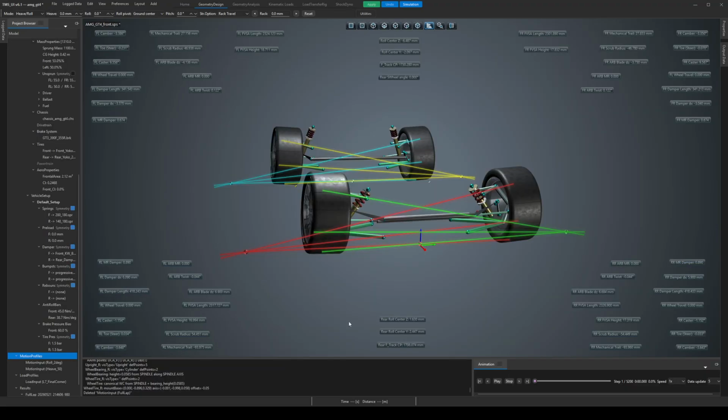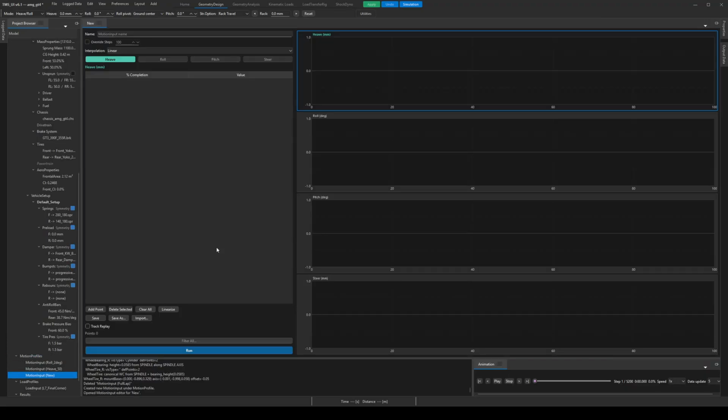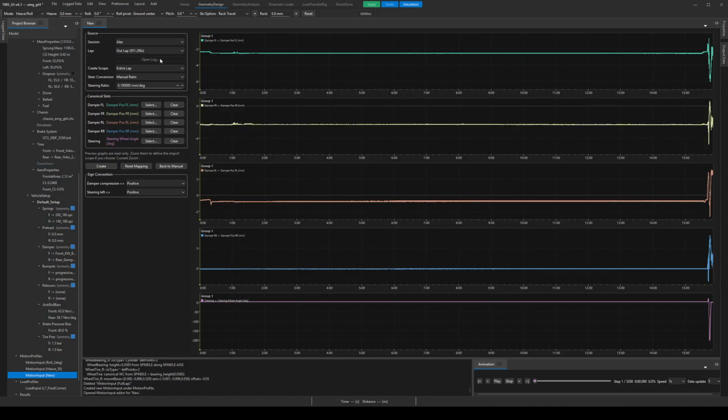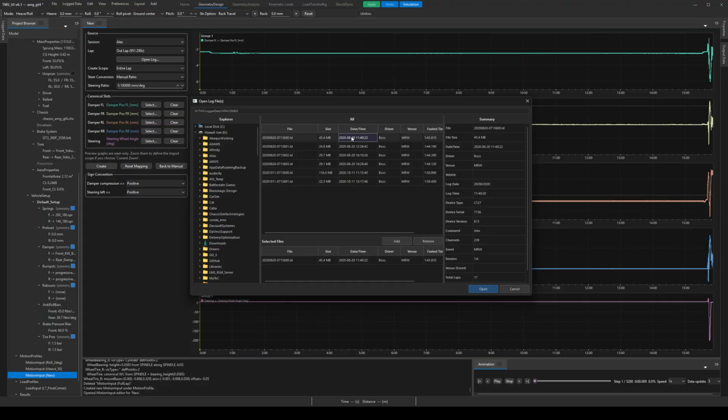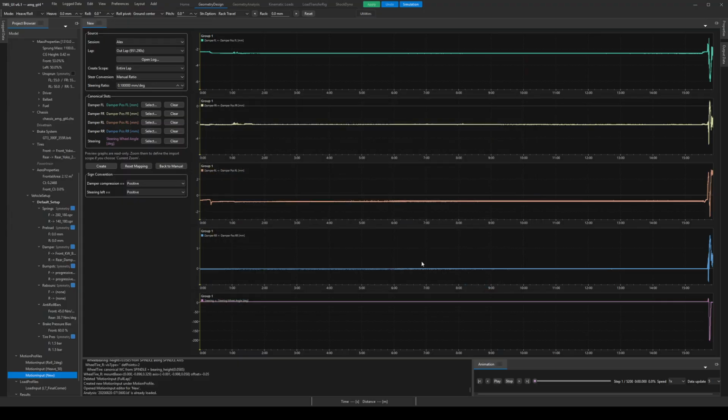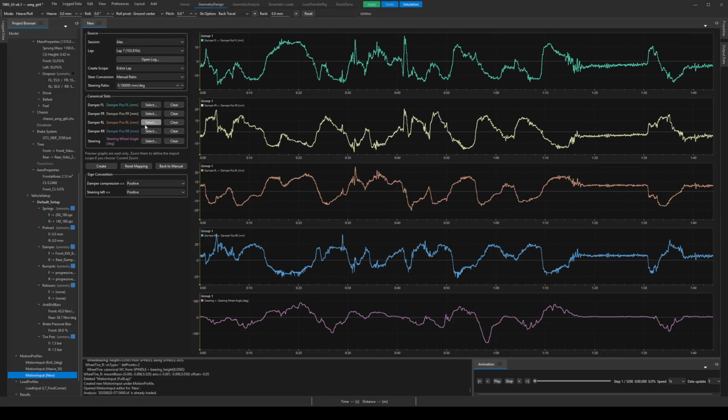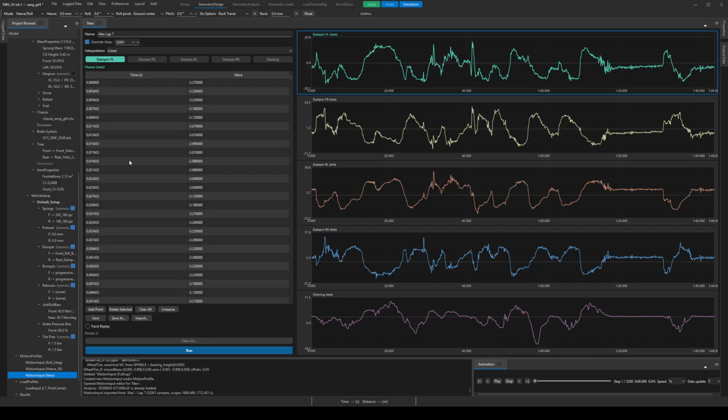Track log data replay is also much more straightforward, and removes a lot of the manual preparation that was previously required in WinGeo. The workflow is simple. In the Motion Input Editor, the user clicks Import, opens a log file, chooses a lap, and the application takes care of the rest of the process. At this stage, direct import of Emotek logged files is already implemented, and exported .csv and .txt files are also supported.